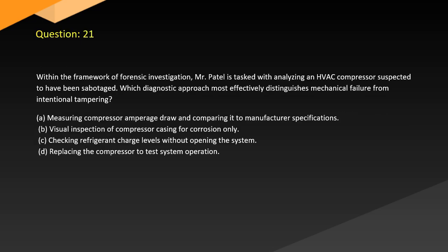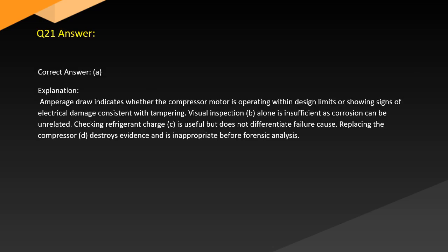Question 21. Within the framework of forensic investigation, Ishta Patel is tasked with analyzing an HVAC compressor suspected to have been sabotaged. Which diagnostic approach most effectively distinguishes mechanical failure from intentional tampering? A. Measuring compressor amperage draw and comparing it to manufacturer specifications. B. Visual inspection of compressor casing for corrosion only. C. Checking refrigerant charge levels without opening the system. D. Replacing the compressor to test system operation.